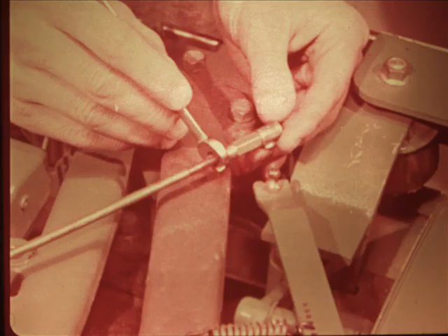With the engine stopped and tension on the governor spring, the stop on the carburetor throttle lever should just touch the stop screw. If an adjustment is needed, just lengthen or shorten the rod at the ball joint.